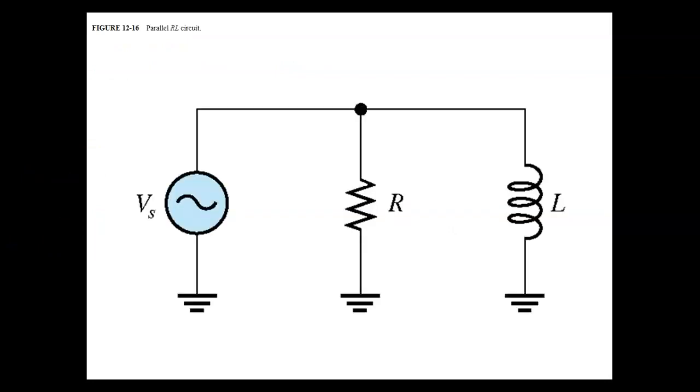A parallel. What do we do here? They're literally not connected to each other. But here we're going to be dealing with current, right? So now we're going to move over to current. What is current going to do? Current is going to lag because voltage is the same. So in a parallel RL circuit, your voltage is constant, so your current is going to lag. And that's why this little thing, Eli the Iceman, tells you a lot of what's going on.